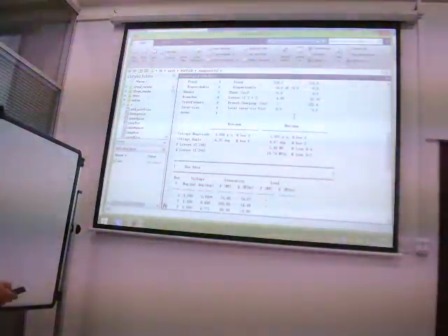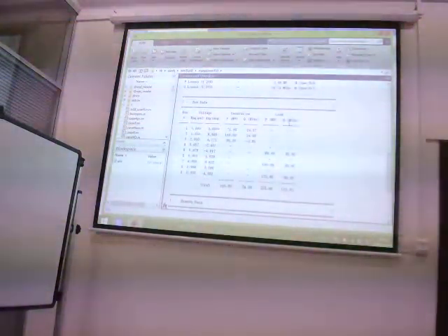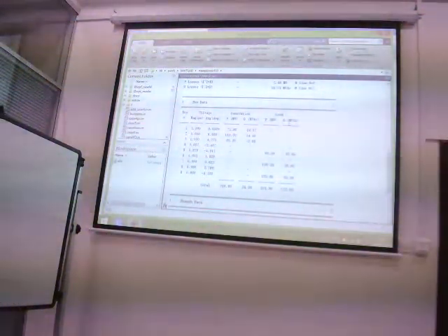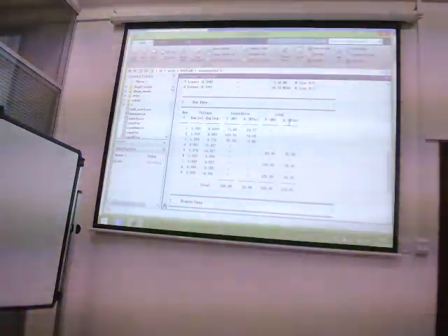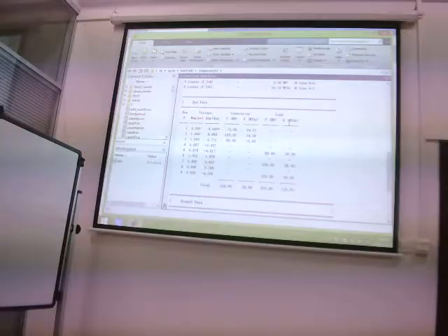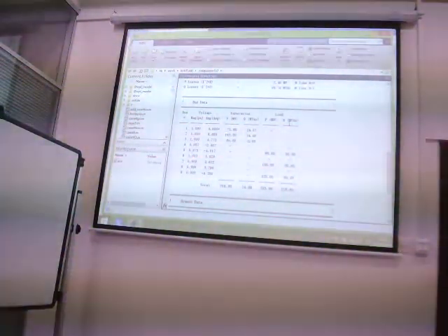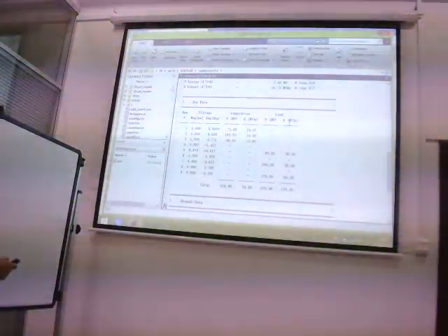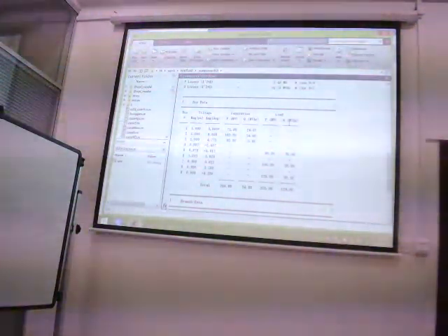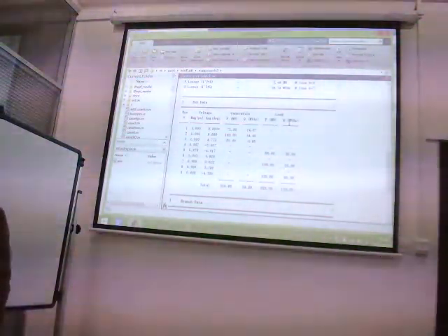Okay, now we can see the data. You can see the data here. For this system, we only have 350 megawatts load demand, and generator 1 has to provide 71.95 megawatts. For bus 2, 163. For bus 3, 85. Generator 1 only provides the minimal value of the generation.